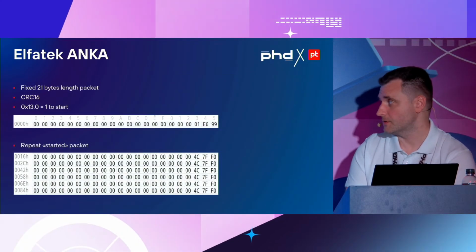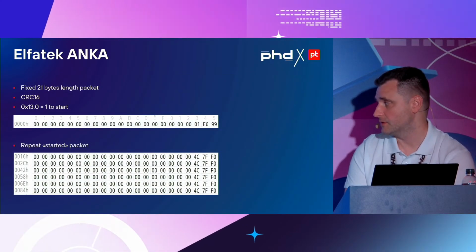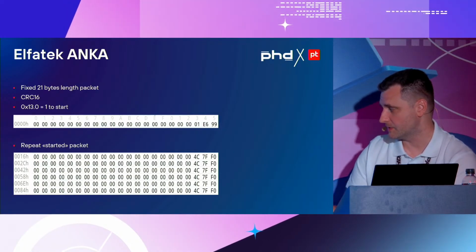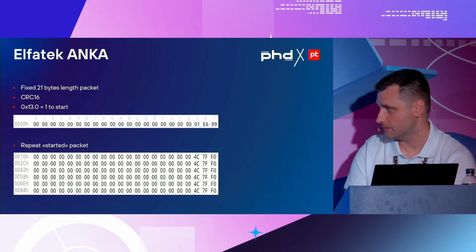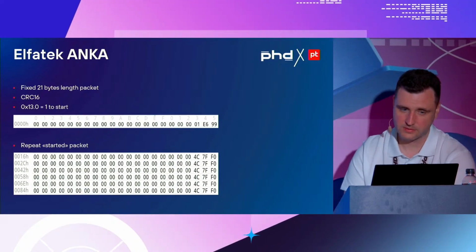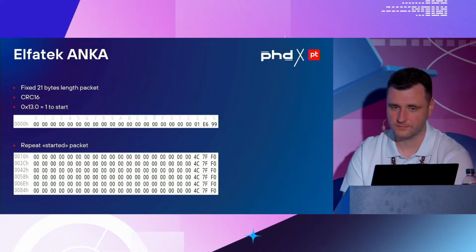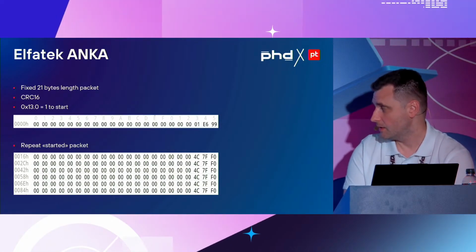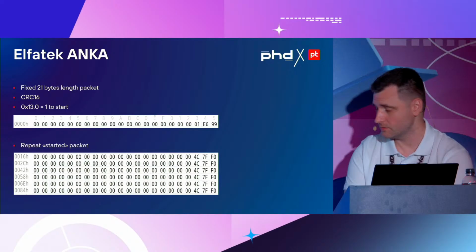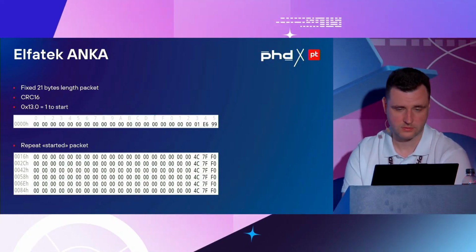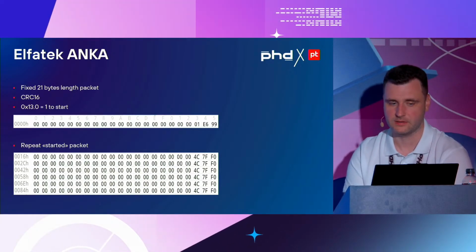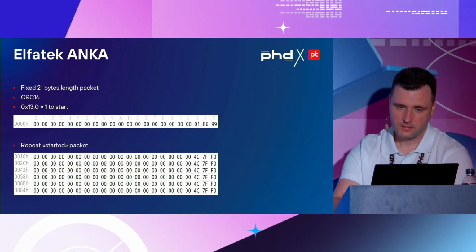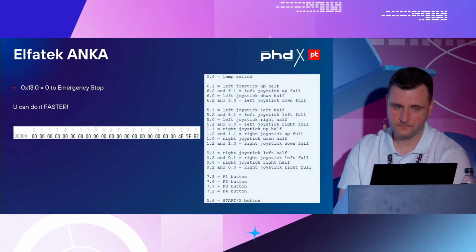Well, the protocol is very simple, 21 bytes with CRC16, and there is also a starting packet, and then you have to repeat the packets with a status assigned to that. So the system is a little bit different, it has a status over there, the current status, whether it actually is in the sleeping mode or not in the sleeping mode.